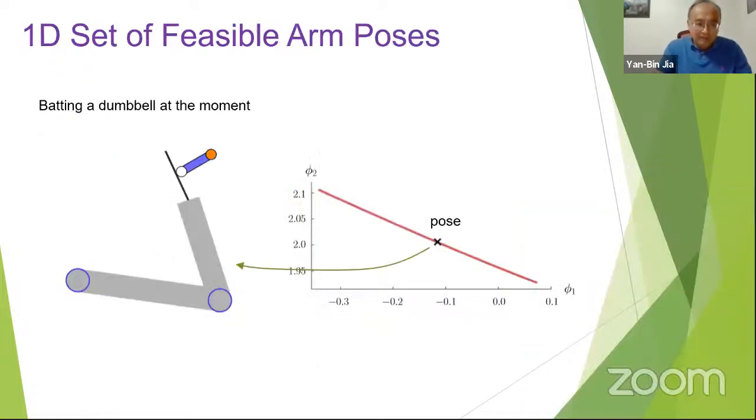But that contact point is not predetermined. So, for instance, if you fix the moment during the flight of the object, the contact point on this dome-shaped object is going to be around the circle here. So you have a one-dimensional set of contact points, which is going to give you a one-dimensional set of poses. That is good because we don't want a unique pose.